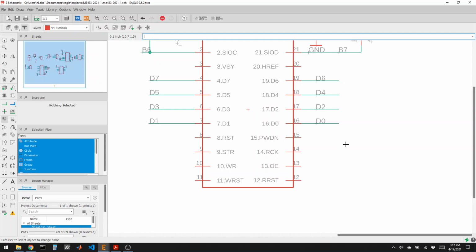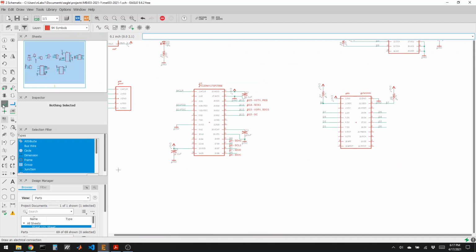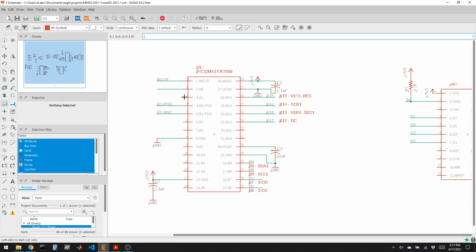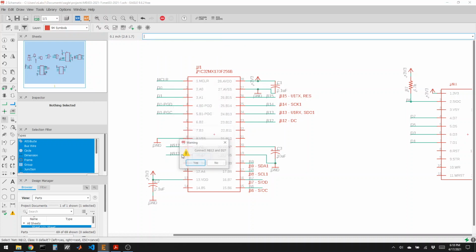So how we're going to read 8 bits at a time. Normally we could do that by saying like port A bits or port B bits. So we'll try to organize these so that some of these are on A and some of these are on B, and they're easy and fast to read. We want to maximize the read speed from the camera. We're going to use A0, A1, A2, and A3. We got A4 too. Yep. So those will be the low bits. A0 is going to be D0. A1 is going to be D1. A2 is going to be D2. And A3 is going to be D3. So we got the first 4 bits.